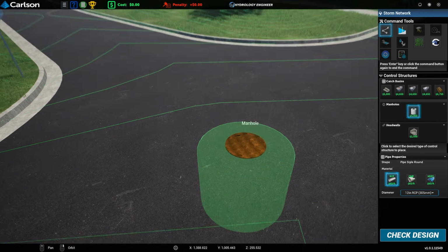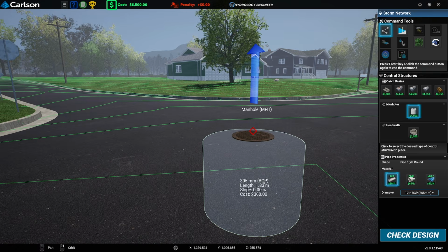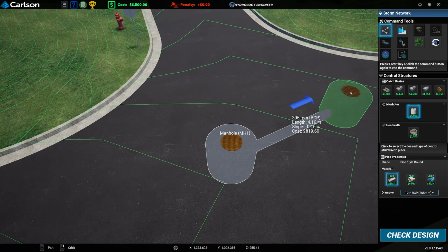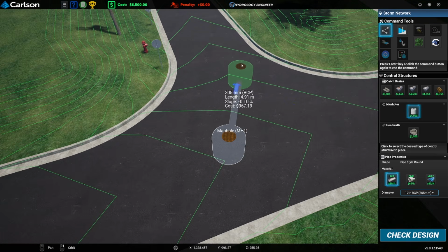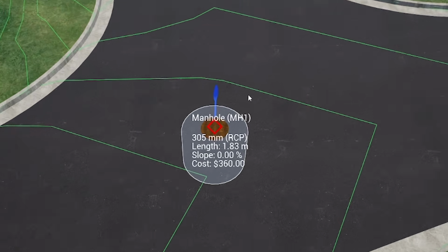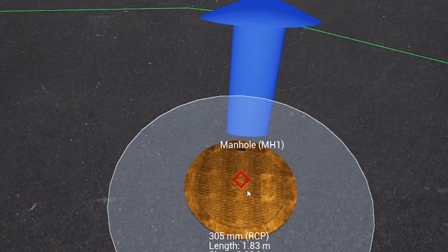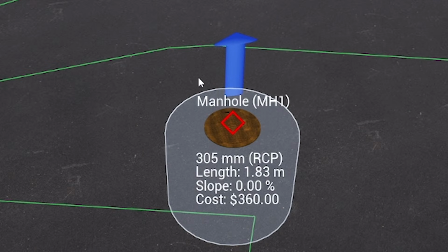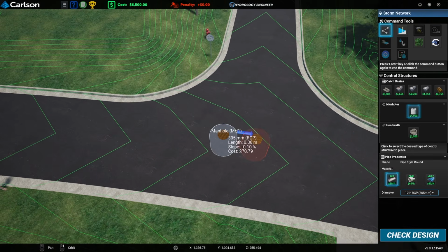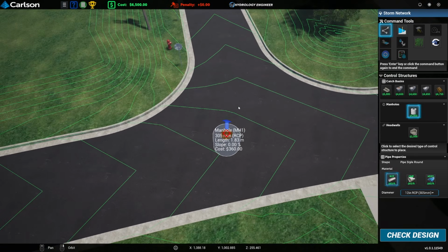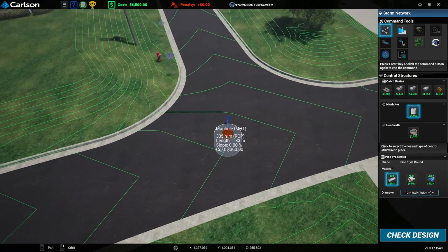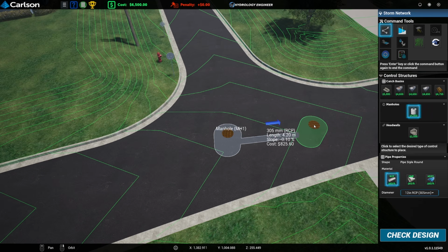So remember, a manhole is this. It just allows you to access pipes. Rather than having the surface water one over here and the foul one there, you'd have them as close together as possible. That's because when we build it, we can dig a really large hole and then put both these chambers in. And as long as your surface water one is shallower than the foul one, then you've basically saved a lot of digging money, because you've only had to dig one slightly bigger hole than 2 separate holes if your manholes were further apart.